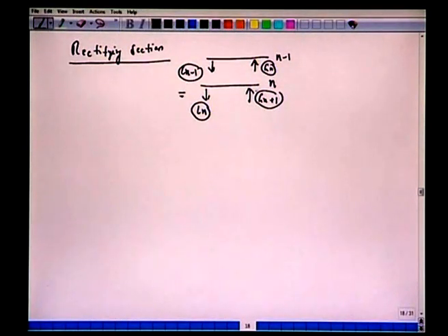Physically, what does it mean? If we have 9 moles per second here, it's also 9 moles per second here. If we have, say, 3 moles per second of the liquid here, we also have 3 moles per second there. So how is this possible? Physically, all it means is that whatever vapor has arrived here, say N moles, condenses, and this will also result in N moles of liquid vaporizing from here, so that the molar flow rate is conserved.